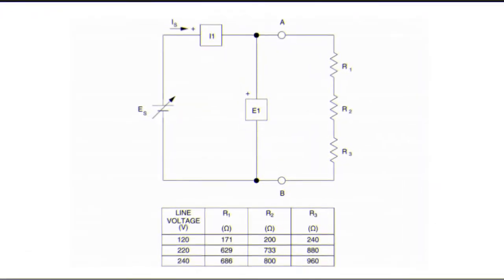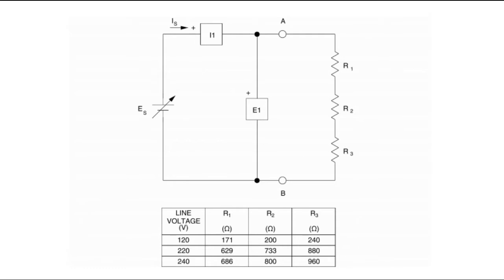The first procedure in performing our experiment is to install the power supply, the DAI, and the resistive load module in the EMS workstation. Make sure the main power switch of the power supply is set to the off position and the voltage control knob is turned fully counterclockwise. Ensure the power supply is connected to a three-phase wall receptacle. Ensure that the USB cable from the computer is connected to the DAI.